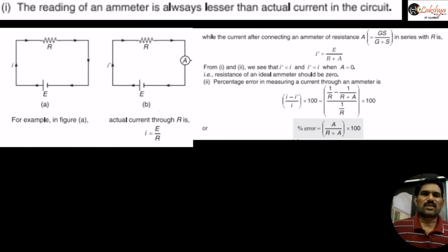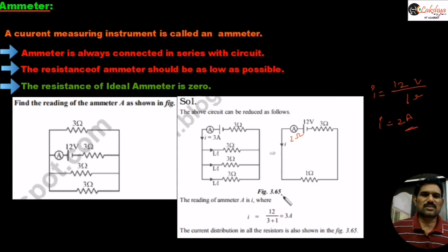So for example, let us take this example here. If you want to measure the potential difference across this circuit, for this we connect some resistance here, that means we connect a voltmeter here to measure this potential difference. If the resistance of this voltmeter is infinite, then no current flows through this voltmeter. Whatever the total current flowing here, for example let us take 3 amperes flowing here, there is no resistance, and so 3 amperes is flowing here. And so this voltage should be 3 volts, right? That is the IR value. If it has infinite resistance, then only it reads this IR value as 3 volts.